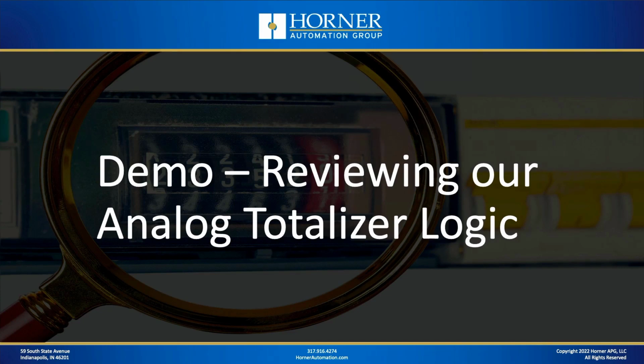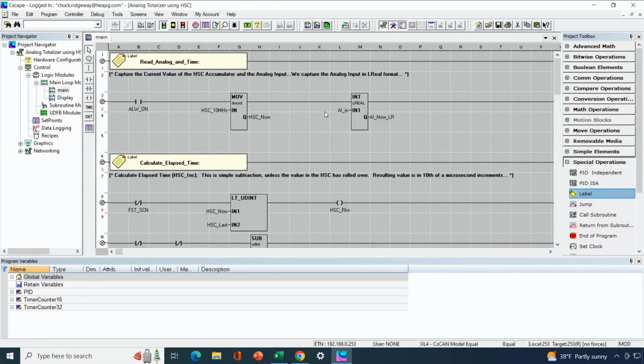That's the logic we're going to need to create. So what I have done is I have already coded this in a variable-based Cscape program, and I'm going to review that with you now. Here's my program. We're going to walk from top to bottom, and I'll show you what we've done here. First of all, it does require that we configure the high-speed counter.